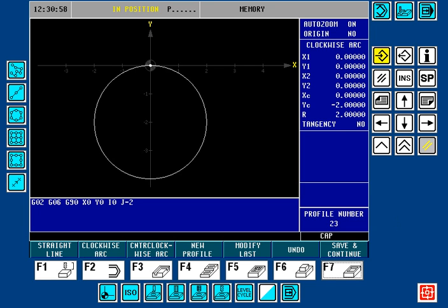This now completes the discussion on error in profile data. If when you're creating profiles you find yourself with an error in profile data, again, you'll have to become flexible on your endpoints by either allowing the control to solve them or leaving some values blank for either one value for the center or the radius, and let the control solve those values if it can find a solution.